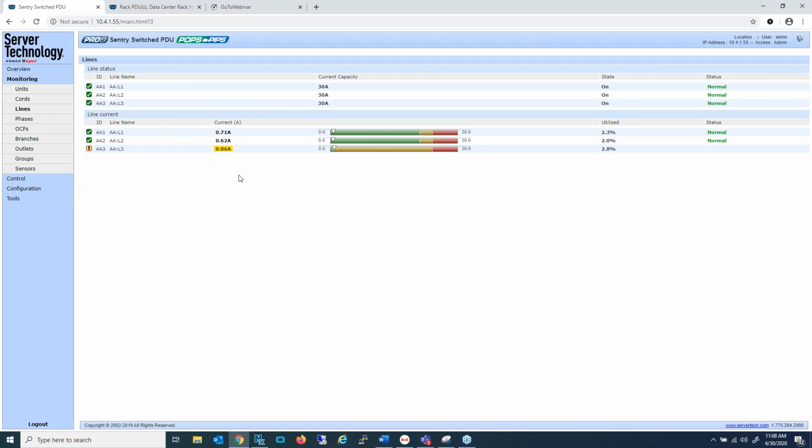So, this same page also shows you the true real-time measured current. Now this is a PDU in the support lab that has very few devices attached, so I am not in jeopardy at all. Again, this is just false, the one that is flashing an alarm. I am not in jeopardy of overloading an upstream circuit breaker. One additional note is that if you are practicing redundancy, you need to think about a half capacity rule. And we'll get into that next when we take a look at where you set the thresholds.